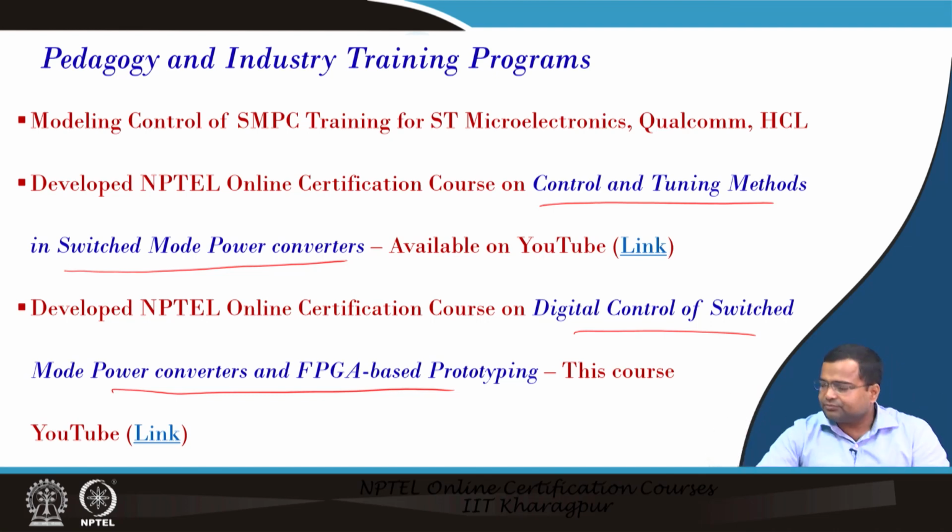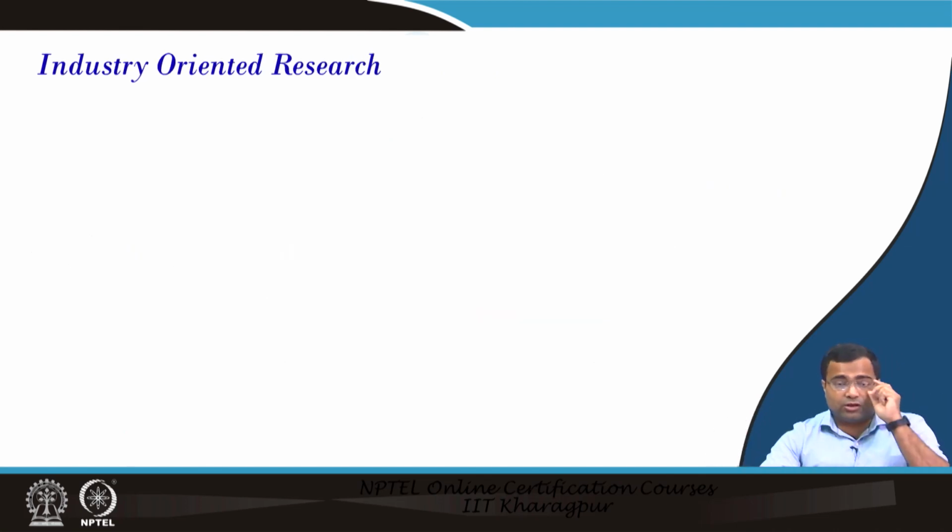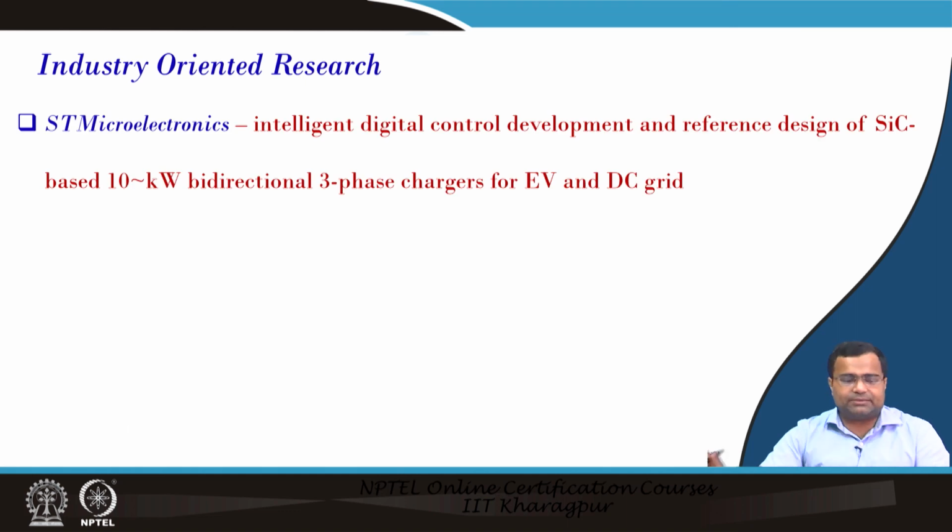We are also carrying out industry oriented research. With ST Microelectronics we are working on intelligent digital control development as well as reference design, and a SiC based high power bidirectional converter for EV chargers and DC grid.